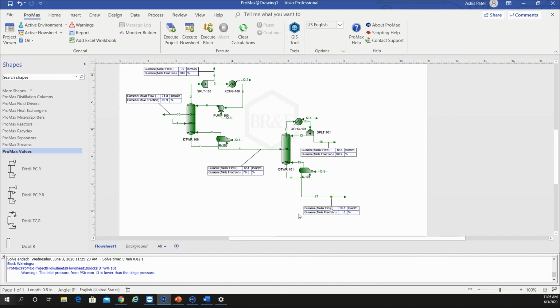And ultimately, the purity of the cumene here is going to impact the heat exchanger duty in our reboiler. So you'll want to observe that value and see if it's reasonable. At the moment, we're processing about 1.4 times 10 to the 7th BTUs per hour. So that can be considered a high value. If that's too high for what you have, then you know you need to relax some of the specifications. And that's just the difference between design and what's feasible.